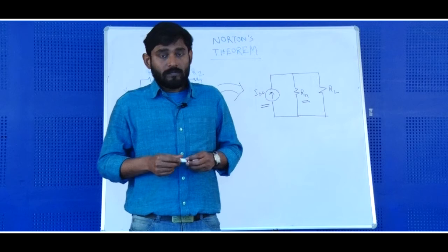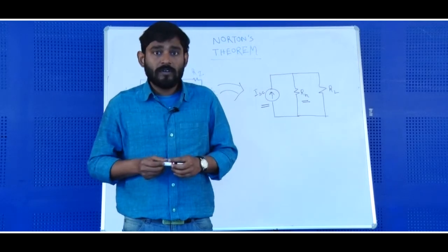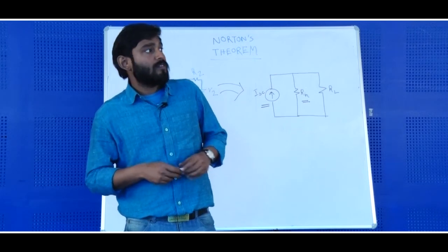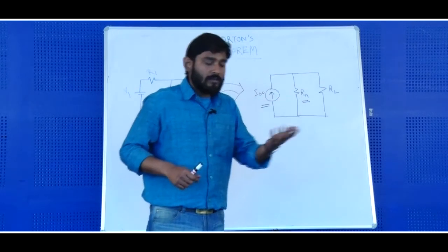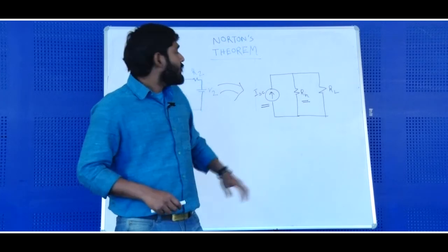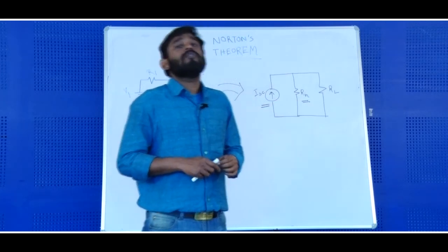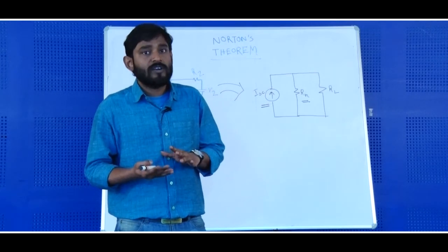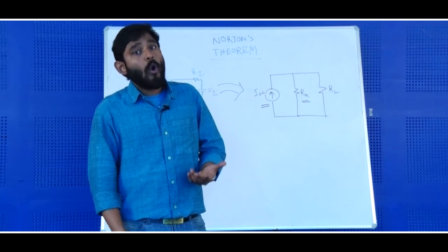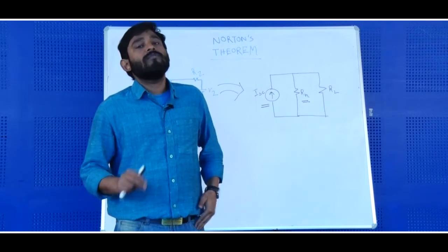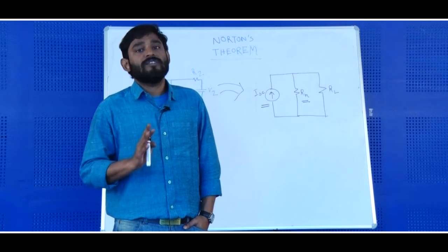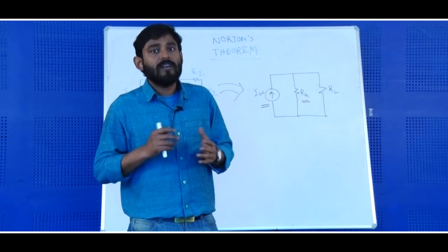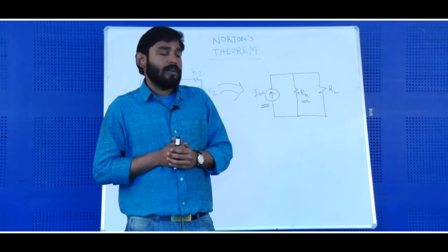And in this case also, this Rin represents nothing but the characteristic of the circuit itself. Why? Because, while doing this discussion you will come to know, this Rin is nothing but the total internal resistance of the circuit. That means it can only be changed if the value or the arrangement or both of the circuit's resistances are changed. So, this Rin represents the characteristic of the circuit itself.